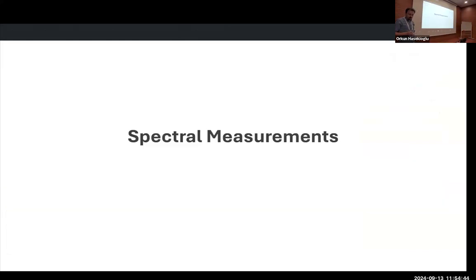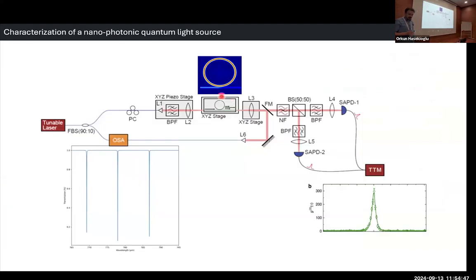As you know, if we try to couple the laser to the waveguide directly, the dimension of this waveguide is usually very, very narrow, for example 500 nanometers. Due to diffraction conditions, you cannot reduce your spot size unless you use very high numerical aperture lenses or very short wavelength lasers. So you will also need to implement some fiber coupling nanophotonic structure here. I'm not going to go into detail, but from the previous talk, there were grating couplers, which are the most popular today.